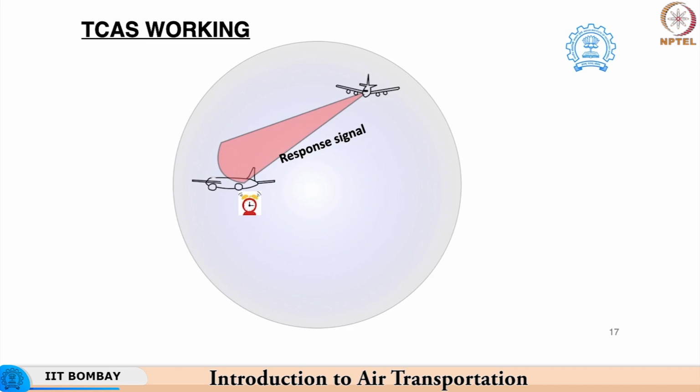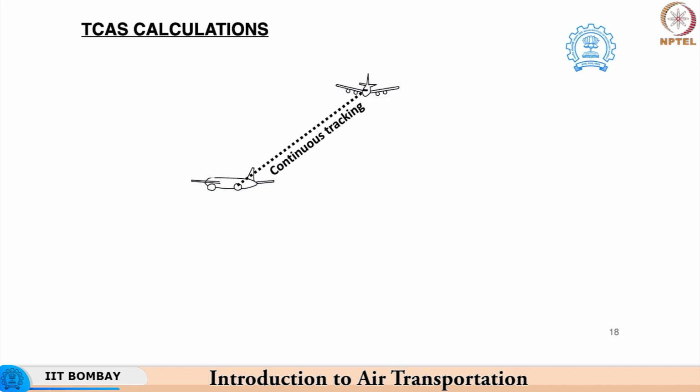Moreover, there are other systems included in the TCAS computers, including the system that determines the bearing of the aircraft with respect to the bearing of the intruder aircraft, and the overall altitude difference between the two aircraft. These systems act simultaneously on both aircraft, and it follows a series of calculations that the TCAS computer carries out simultaneously.